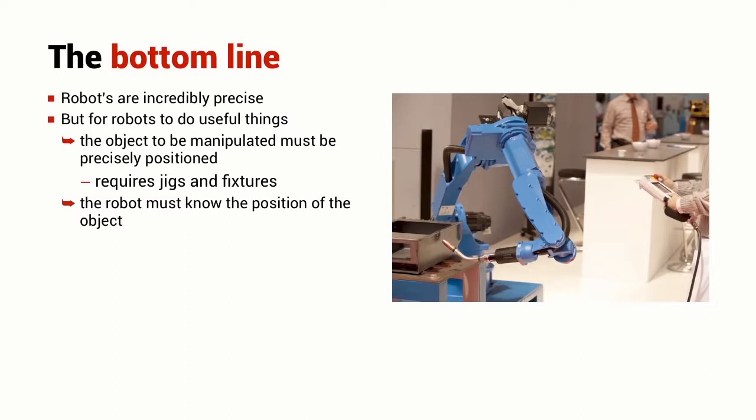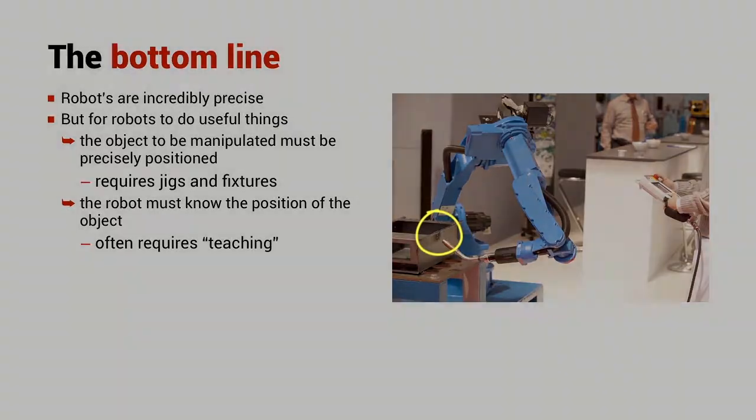In this particular picture, you can see the operator doing this. The operator is holding in his hand what's called a teach pendant. It's a large box covered in buttons, and by pushing these buttons, he's able to drive the robot's tooltip to the required location within the workspace.